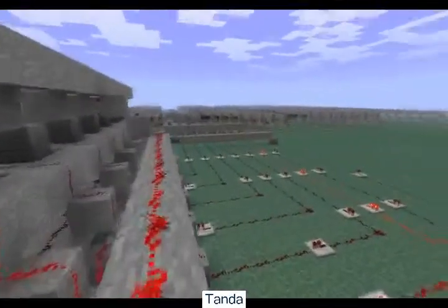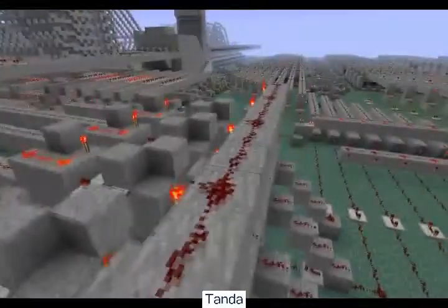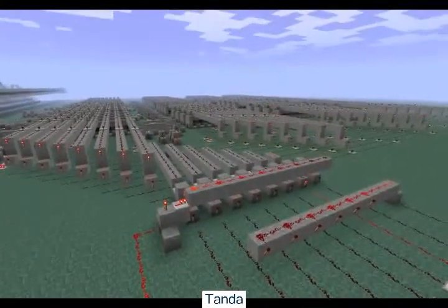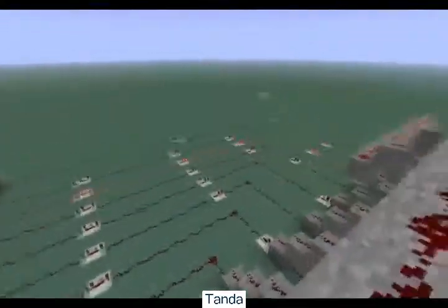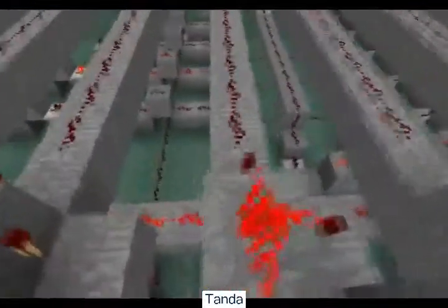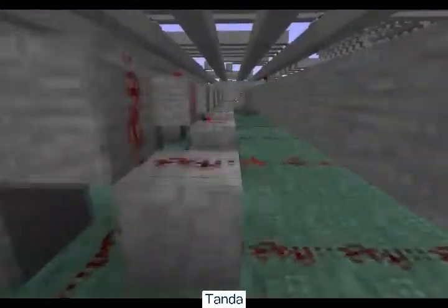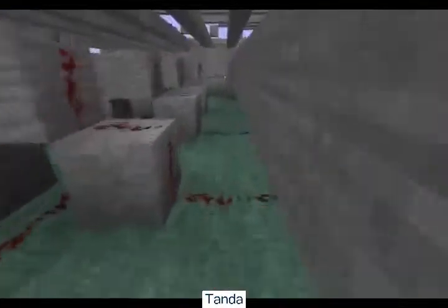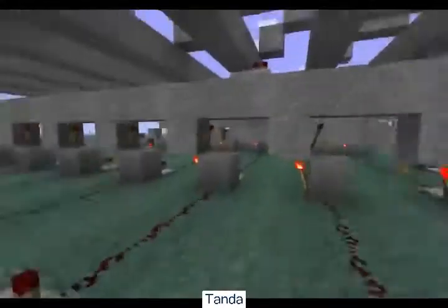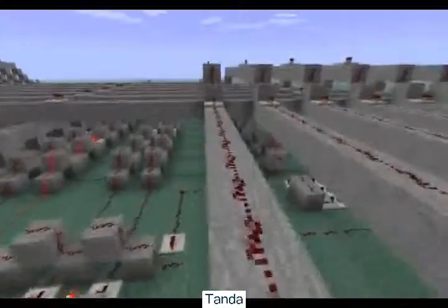Okay, so the instructions come down here. Activate relevant wires over here that will output the program command from the large area of memory over there. Each one is 16 bytes, so I have 64 bytes in total of memory. These here are two sets of registers, each 8-bit, top and bottom. They hold the current instruction, and the wires running underneath here are the instruction, while the ones coming off of it direct that instruction to the area that processes it.